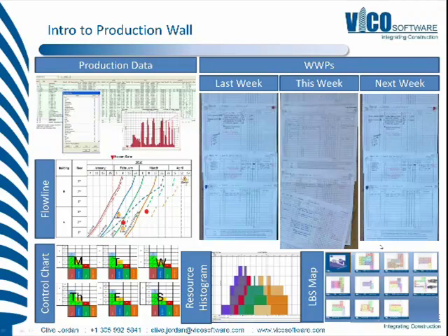And in the bottom corner here we can see a very important part of the process, which is the location breakdown structure. And in each one of these lists, what we're doing in one of the columns is referring specifically to a location within this location breakdown structure, so that we know exactly what the work is and very precisely where the work is occurring. So bringing the data together like this is a very powerful way of sharing and managing that process.